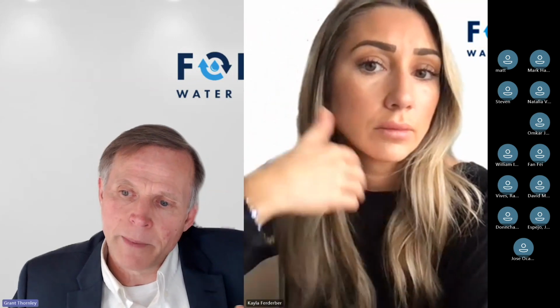But if you go to a titanium oxide, which is more conducive to ion exchange, I can go significantly lower. I could go down to around 50 ppm. I think it's a good question because it differentiates lithium aluminate from titanium, based on my characterization.